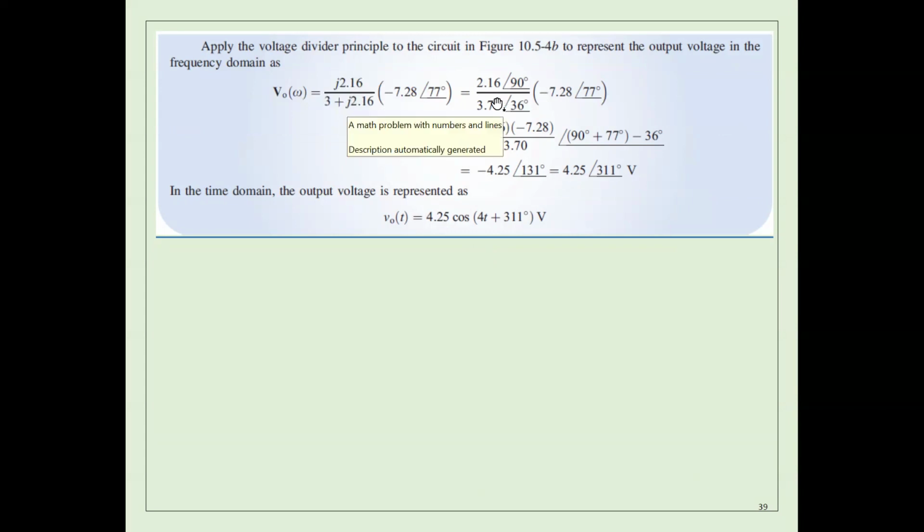Now we are going to come to the nice part. You need to convert everything here from complex to polar because it's easier. Once you do that, for multiplication, you are multiplying magnitude by magnitude divided by magnitude, as you see here. For angle, you add. I'm multiplying these two numbers together, so I'm going to add this angle to this angle minus this angle. So this is the result.